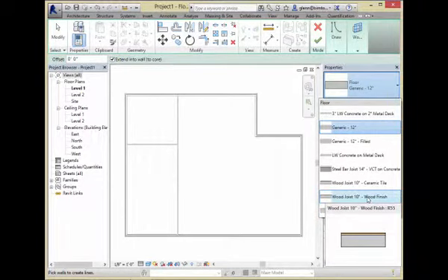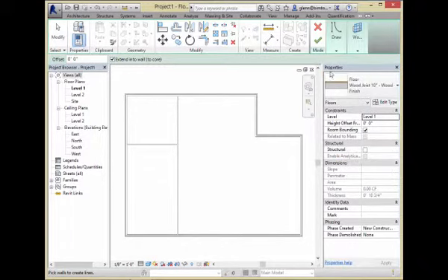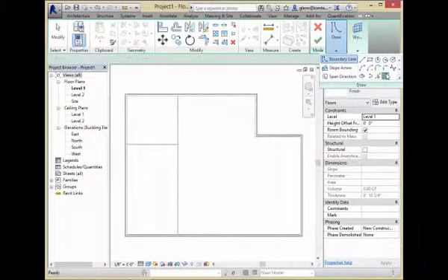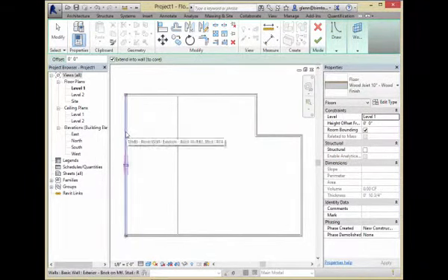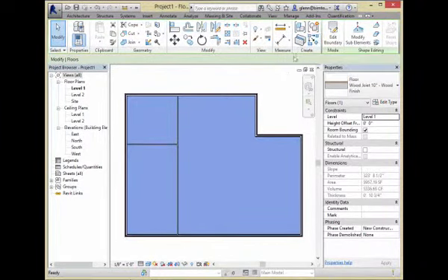And you can actually see it has these layers. It has framing, it has subfloor, it actually does have a little bit of finish floor in there. So if I choose that one as my predominant wood type, I'll draw the boundaries just the way we learned to. I'll go to the cores, bring it around, and I'll finish that.